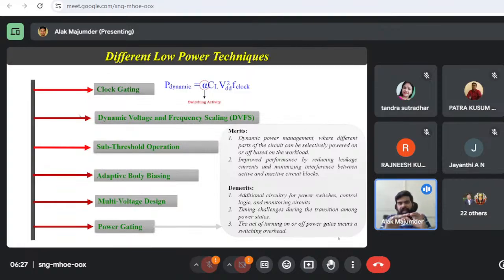But this 10 milliampere is coming from a big network of circuit. Now I need to draw that 10 milliampere current using a series or a parallel connection of PMOS or a parallel connection of NMOS. So the sizes of those devices have to be quite large.